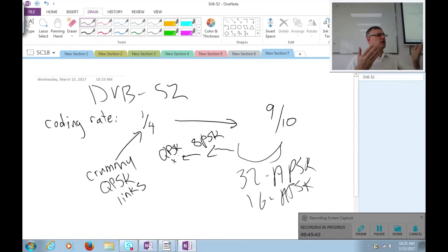And then if you start getting worse, what do you do? If your channel gets noisier, what do you do after you hit QPSK? Well, there's no way to go down. I could go to BPSK, but that doesn't really help much. I get kind of that extra channel for free on QPSK. So I'm kind of limited. I can only send so many bits per second. So what you have to do then is just start to add more and more redundancy. Lower your coding rate, add more redundant coding bits, and this will allow you to overcome the noise up until you hit the channel capacity of the link, and you just can't send any more bits. It's too noisy to send digital data at a minimum specified bits per second.